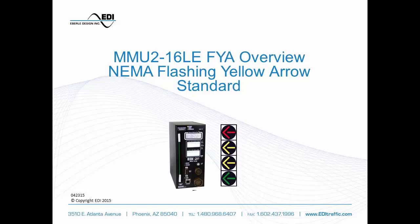We are going to start off with a little background material on flashing yellow arrow, get into the need for it and the complexities of programming both the controller and the MMU, and then we'll see some examples of how the NEMA standard has defined the operation with respect to the MMU, and finally how we program the EDI MMU2-16LE smart monitor to configure it for flashing yellow arrow.